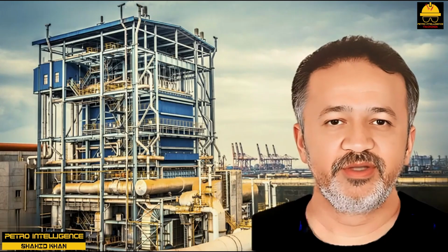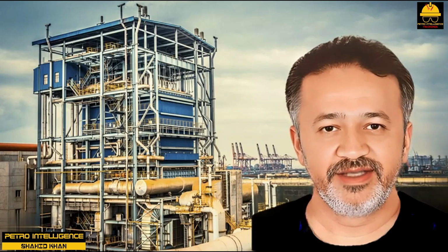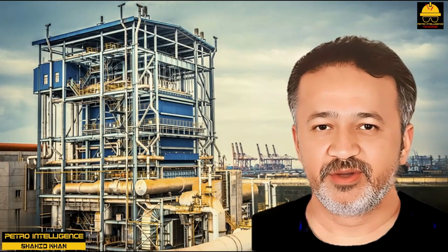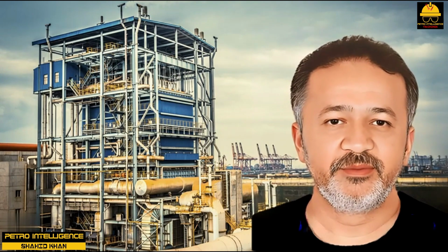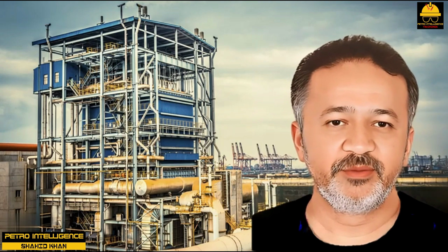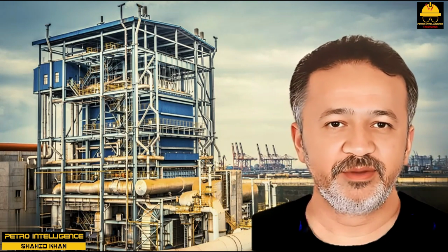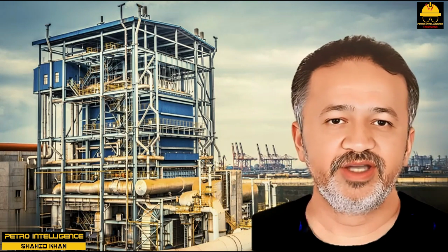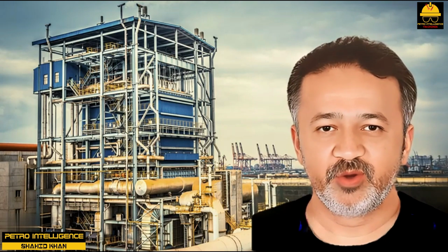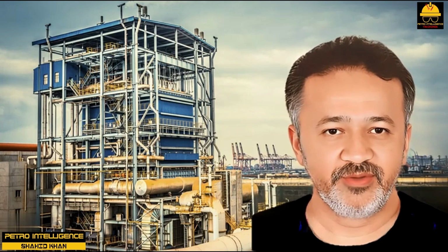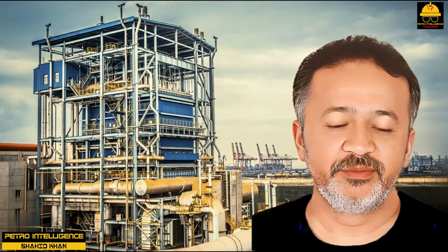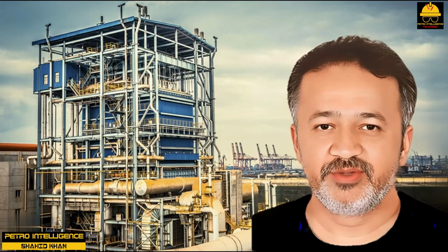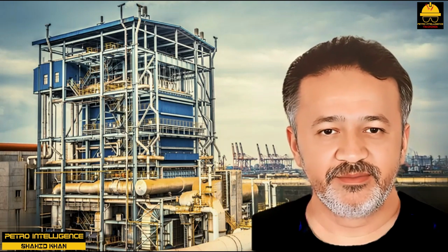Use of twisted tubes. Twisted tubes are used in crude preheat with crude on the tube side. The main benefit that is found seems to be the increase in surface area, typically 40% more surface area in the bundle since there are more tubes in the bundle compared with a conventional bundle that would fit the same shell. Actual experience shows that the twisted tubes may foul more readily and will plug if fouling deposits are from particulates in feed. But the twisted tube design does work in this service to combat fouling if deposits are formed as a fouling film inside tubes.